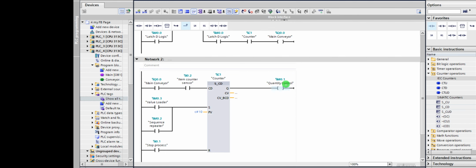output of the figure. Then this one, I'm going to use to activate this output. This output is not the value counted. It's not reflecting the value counted. It's reflecting the activity of this. It's reflecting that this is on or this is off. When this one is off, here will go off. When this one is on, here will come on. So here is telling the activity that is going on here. This one is telling you that this counter is on or this counter is off. So it's giving the status of the counter. So I can use the status of this to activate another bit or deactivate another bit. So that's the essence of this.